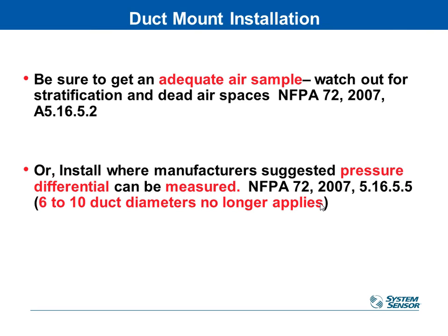You don't want to put any type of sampling devices, whether it's duct smoke detectors or temperature sensors or anything like that, right at the end of an elbow, because the airflow will not be coming through there in a uniform fashion, and you'll get dead pockets where there's actually no air movement at all. So you're better off putting it 5 to 10 duct diameters downstream of any of those objects.